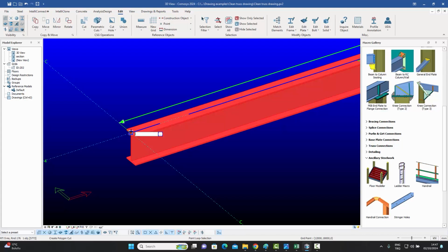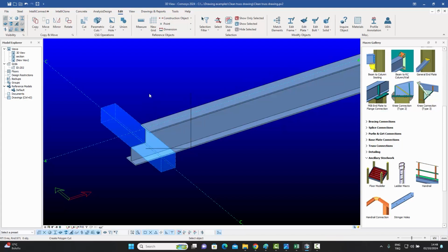So let me start from there, then say dx 150. And then on the new point, I just hover over that. As you know, I press enter, say z minus 150, go down. I hover over this one now. I say dx minus 150, and then I can just go back, close it. Now, you're familiar with this polygon cut, so nothing new over here. But when I select it, you can see that now we have these handles available, which weren't previously available.